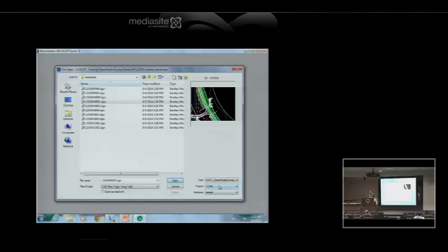But internally, we're going to transition ODOT to a user, which would be ODOT 2014, I think, or something like that. And then we are going to transition ODOT to using a true PCF file. So there will be a site configuration file that Mark mentioned this morning. The site configuration file will define all the variables that are relative to ODOT. The project configuration file will only define variables specific to a project. There are a couple things with OpenRoads defined by configuration variable that will vary from project to project. That's the need to move to a PCF for ODOT.